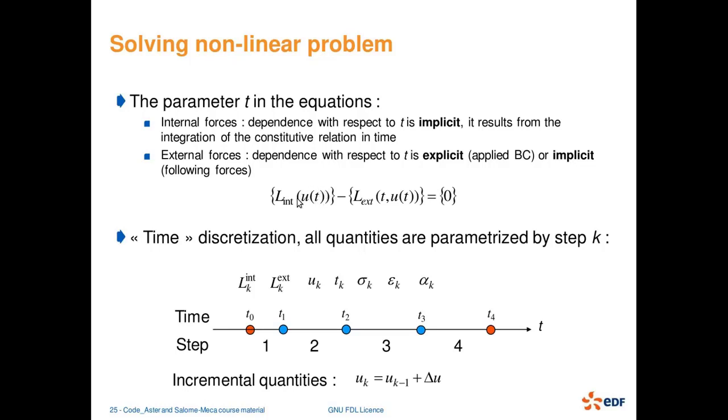And due to equilibrium, at any time step t, my deformation must be such that the internal forces generated due to that deformation and the external force applied at that time instant, their difference must be 0 or very close to 0. Otherwise, equilibrium will not be achieved.